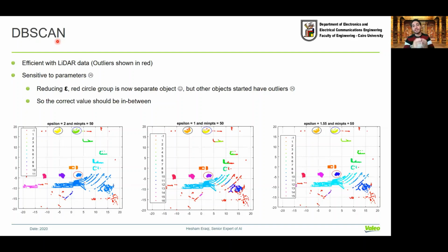Actually, the laser scanner is sending several beams, and the angular difference between a beam and the neighboring one is very, very small, because the laser characteristics allow us to do this while not having so much interference between the different beams. This is not, for example, achievable if you rely on a sonar or a radar or an ultrasonic sensor. So if you try to visualize what's happening in top view, usually you have a car here and you have your sensor here, and your sensor actually transmits so many beams like this. Most probably this is a road.